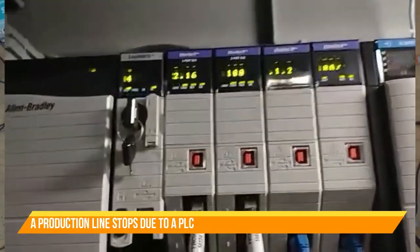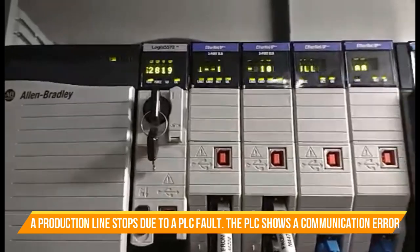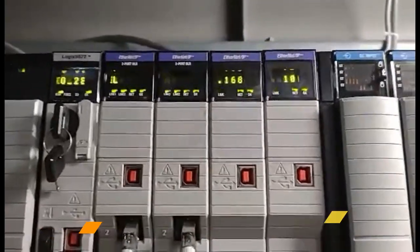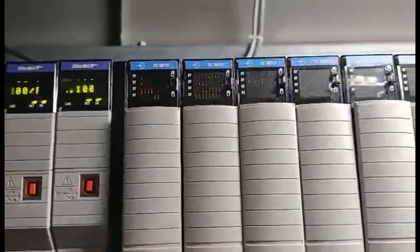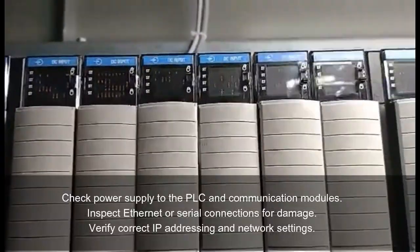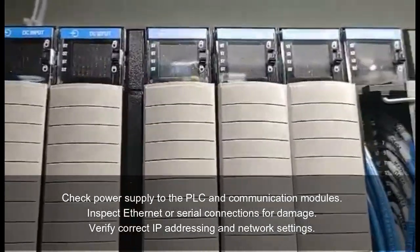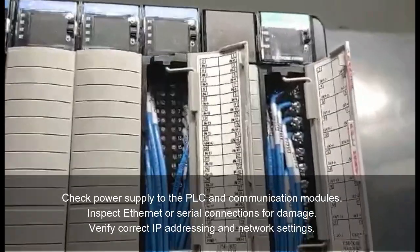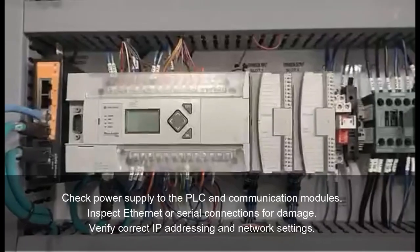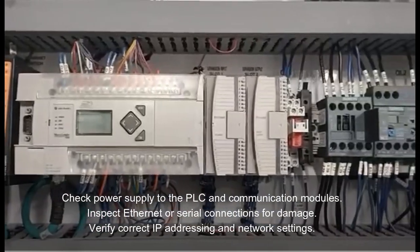Next question. A production line stops due to a PLC fault. The PLC shows a communication error. How do you diagnose the issue? Answer. Check power supply to the PLC and communication modules. Number 2, inspect Ethernet or serial communication for damage. Number 3, verify correct IP addressing and network settings.